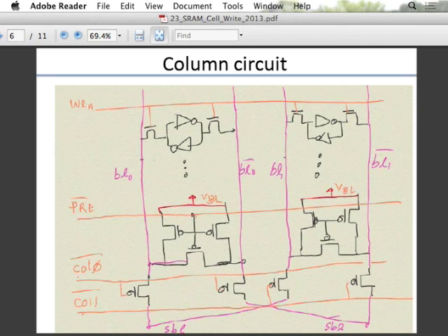But really it looks at the difference between the voltages of bit and bit bar, which means that before you start the read, you better make sure bit and bit bar voltages are close to each other, because of any residual mismatch. Maybe in the previous cycle you did a write where bit line bar was 0, because during a write you discharge all the way to ground. Bit line bar is 0, bit line is 1, and then you equalize. So bit line bar comes up, but maybe it doesn't come up fully. Maybe it has just come up 100 millivolts short. And the next cycle you are doing a read where the other one is supposed to be going low. You see, 100 millivolts is the signal we need to sense anyway. So if you start off with minus 100 millivolts in the other direction, it is not good.